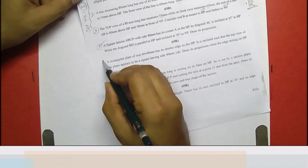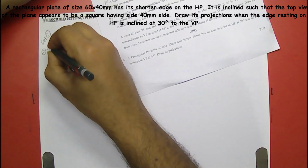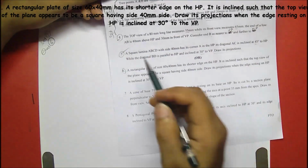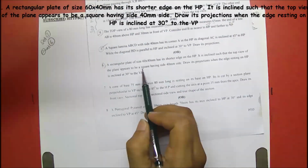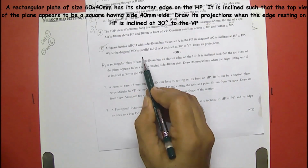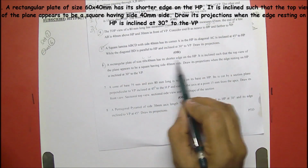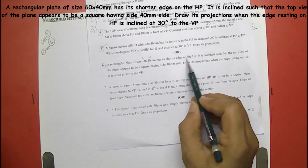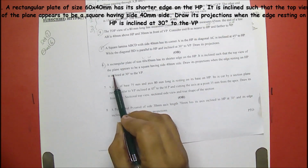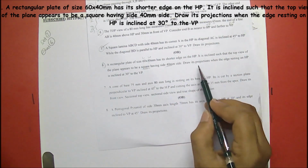Problem 6. So this is the given data: a rectangular plate of size 60 and 40, means length is 60, width is 40, has its shorter edge, that is 40 mm, on HP, and it is inclined such that the top view of the plane appears as a square having 40 mm side.